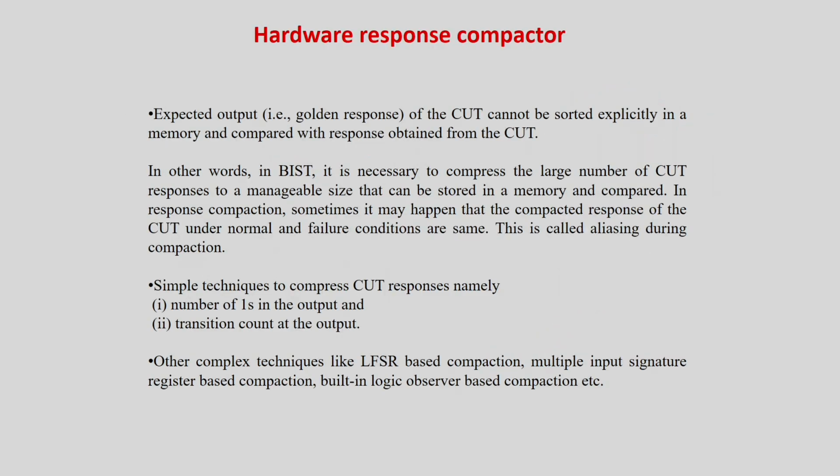But the key thing is that the size is very small, only a few XOR gates will do the trick. That is why LFSRs have become a boon for BIST. I can also say that if LFSRs were not there, BIST was a very difficult problem, because I require a very low area overhead test pattern generator, and that is made possible by LFSRs. So your problem of input generation is solved. You have an LFSR, it will generate the maximum spectrum of inputs and you are happy with it.